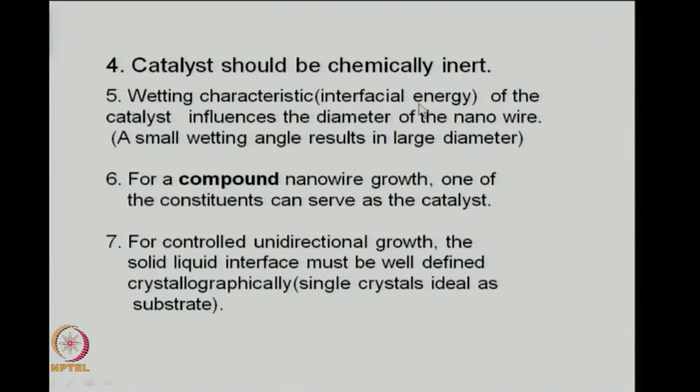So, the interfacial energy or the wetting characteristic of the catalyst influences the diameter of the nanowire. The diameter of the nanowire can be related to the contact angle, which also depends on the interfacial energy of the liquid and the solid.